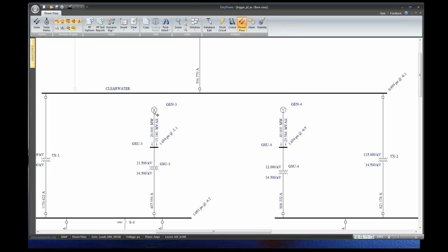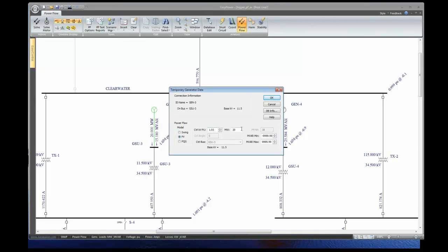All right, so just remember that you need to select the right operating conditions here before you run your power flow for the generator. And these settings only affect power flow. They don't affect short circuit calcs or arc flash or anything else. This is only for power flow. So normally the default's going to be this PV. You might switch to PQG. If the generator is running isolated, it'll need to be a swing source.